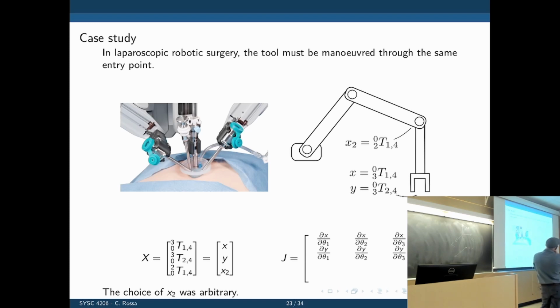But instead of going with an orientation, what I could do here is to specify a third point. If I want this robot to go, let's say, on an angle, like this, I want to place the end effector here, but in this orientation. What can I specify? I can specify the end effector's x and y, and I can take another point, any point, and say I want this point to be here. I'm choosing here to take the end of link 2